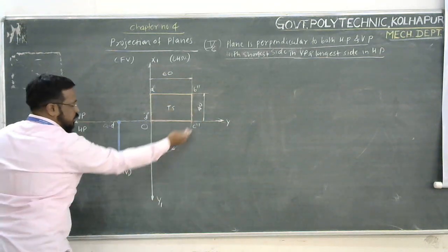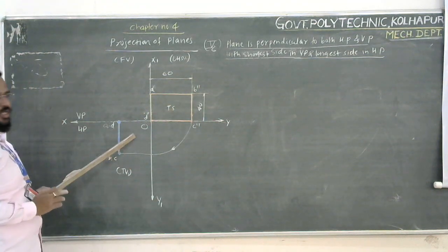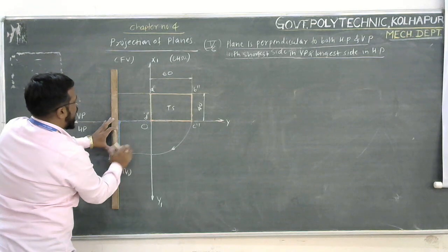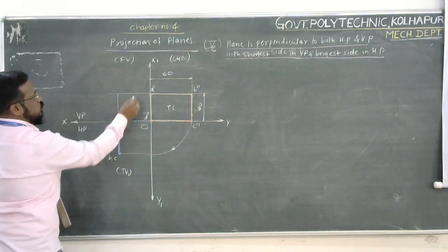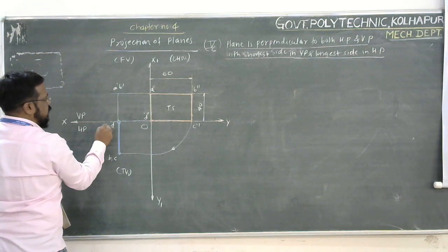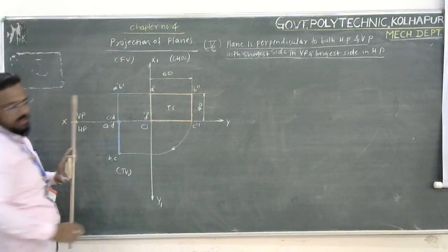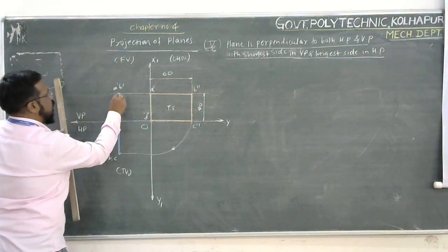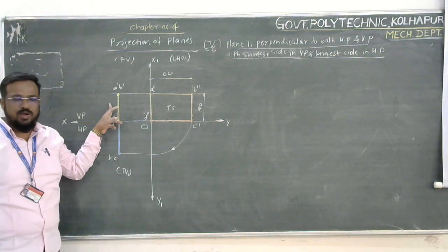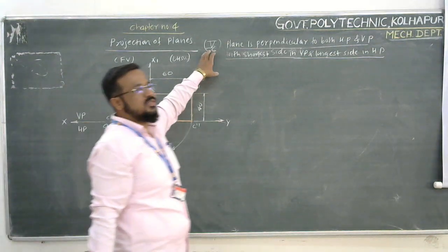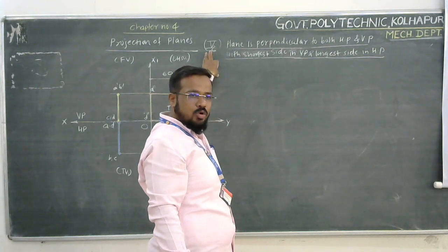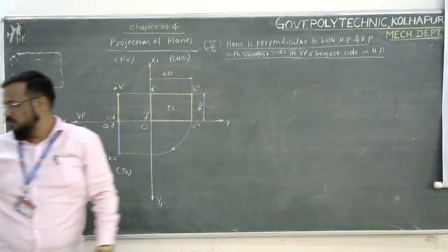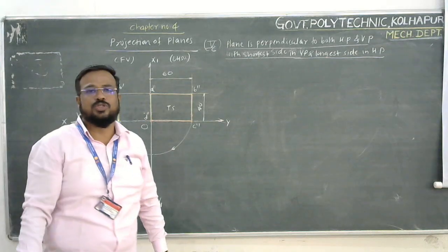If you project this to the back, no doubt this will be the top view. There will not be a change in the top view. But in the front view, if you project this back, you are going to get the front view immediately starting from XY. So this is your point A dash B dash. And this itself is nothing but point C and D. So front view is represented with the help of a yellow line. So this is the way in which you can represent the front view, top view and side view. So this is 5C condition when the plane is no doubt the profile plane, but its longer edge is in HP and its shortest edge is in VP. So these are the four positions of the plane.